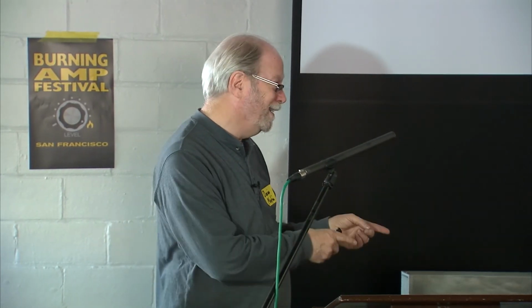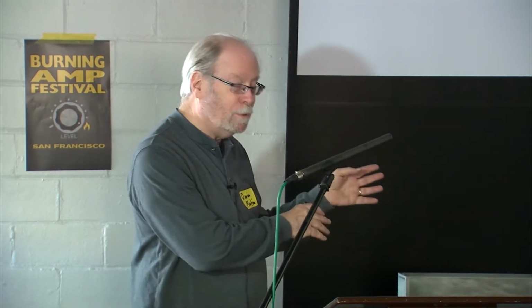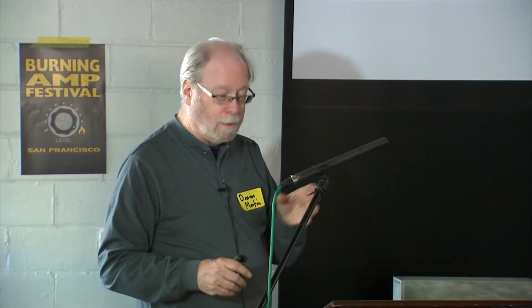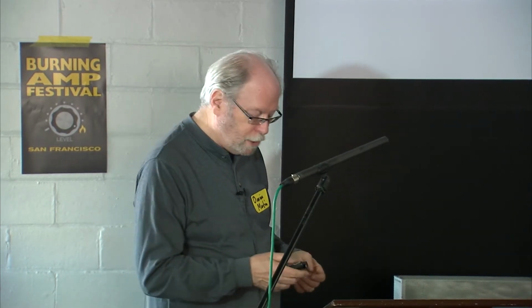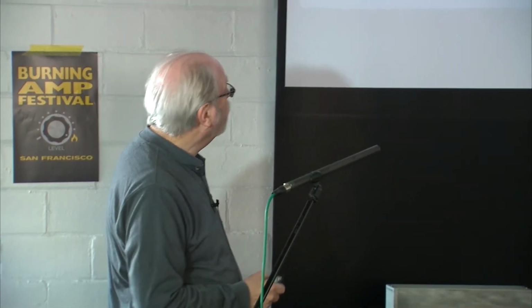And then the third option, and this also goes back, is the manual spectrum analyzer, called a wave analyzer in the old days. This is an instrument where you would literally measure the fundamental, and then you'd tune it up and measure the amplitude of each harmonic, manually finding it and writing it down, and then doing a lot of manual calculations. So if we go forward, here's the traditional notch filter analyzer.